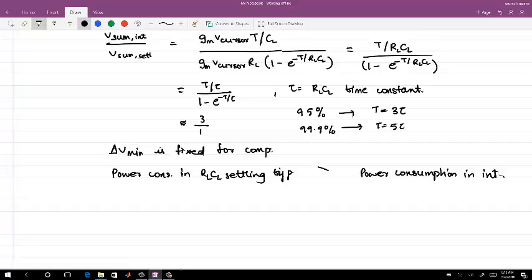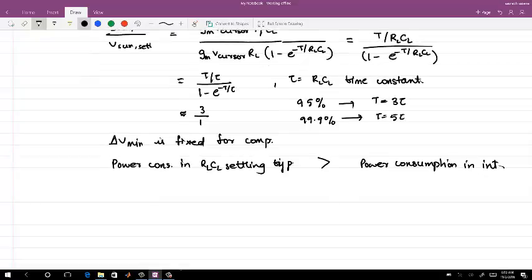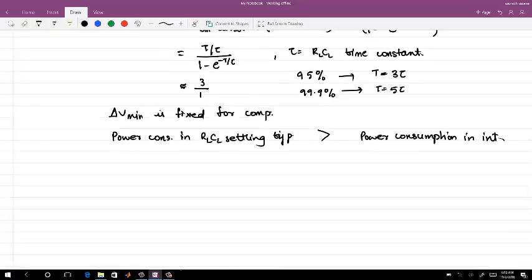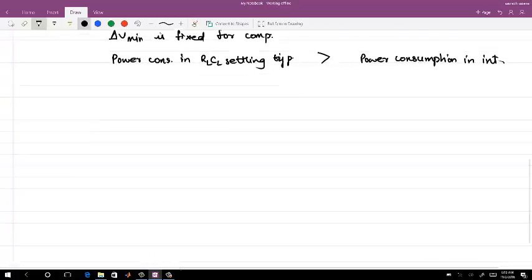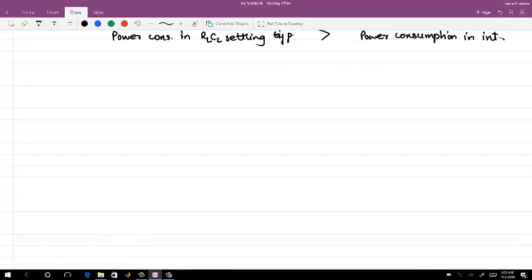In an actual implementation, that might not be the picture, because of some other things which we'll look at. But this is very good in the sense of pursuing the integrating type further: what are the problems with the integrating type? Let me show you the implementation. No one has asked the question: if you just keep on integrating on some capacitor, the voltage will just go and saturate, right? How do we deal with that? Discharging the capacitor will take some amount of time.